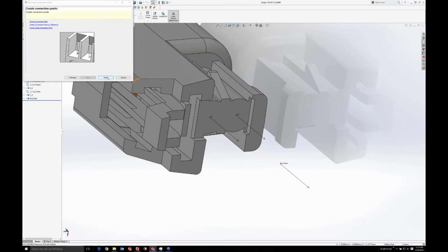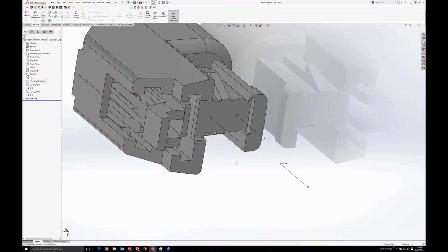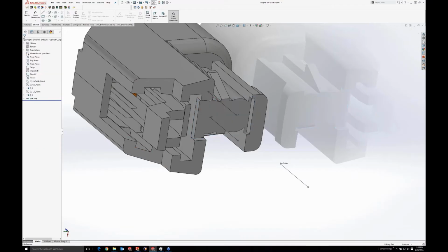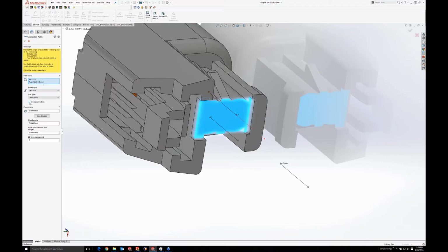For something like this, where these two connectors are, you know, 1/4 inch apart, I generally use 3/4 inch, but that's just my preference from a lot of experience with twisted pair cables. So that's it. I add some connection points. You can add an EW cable point if you'd like, and you can see that these are just regular routing points. They just have special names. So you can still edit these if you wanted it to go the other direction, you know, reverse direction and route through the front of the connector. You can do that right in here, just like you could with regular electrical routing.